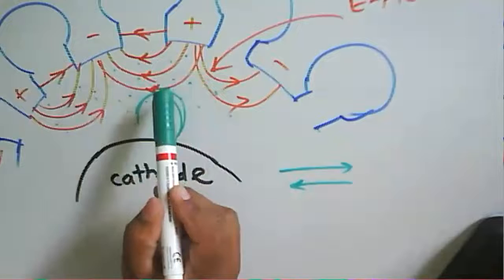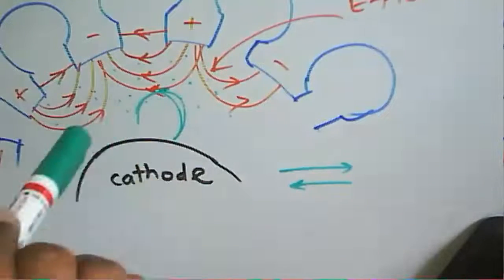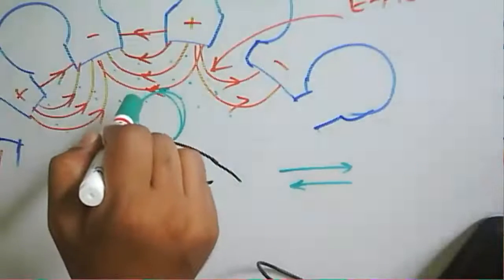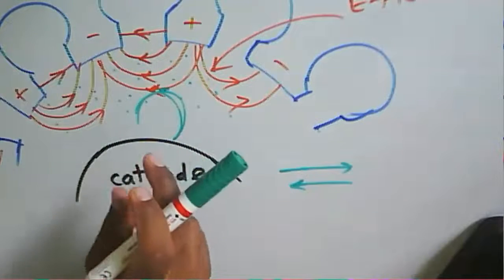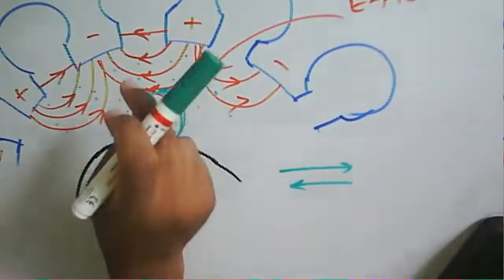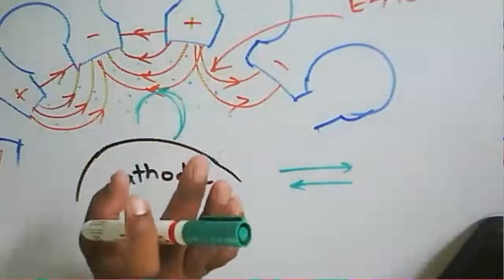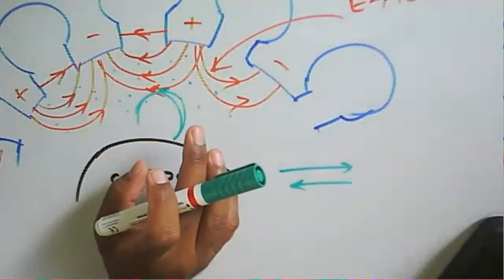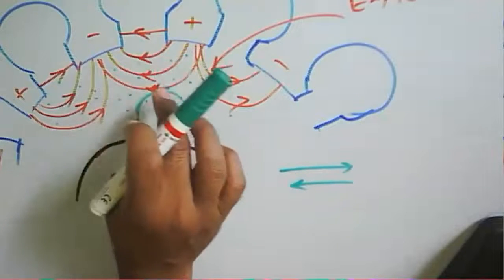There will be an RF field component, which is a tangential field component, and there is the magnetic field. Because of that, the electron is retarded by the field and gives its energy to the field. This is the tangential electric RF field here.